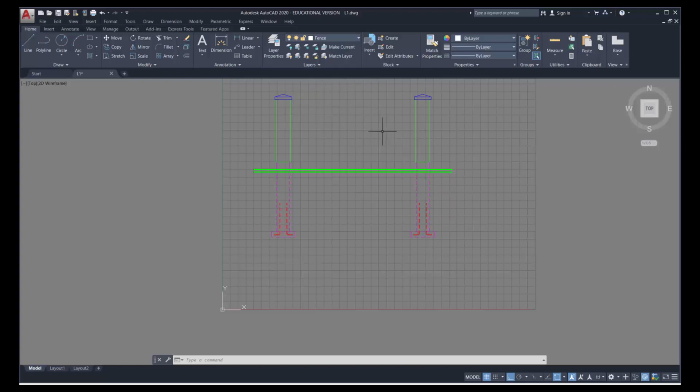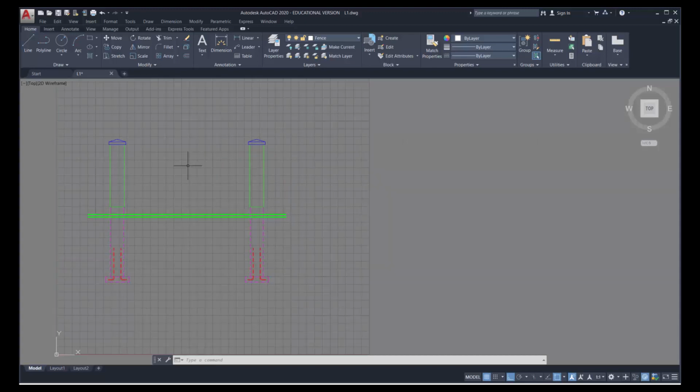And if you take a look at the diagram that's associated with this lesson, you'll notice that the gap between fence pickets is 6 inches. Now the picket itself is ½ inch. That's not dimensioned anywhere. The larger tubes that hold the pickets are 1 inch. So let's draw this. I don't have enough information to draw it in here, because see in the beginning there's a question mark. Now that's done on purpose sometimes, only because each of these gates may be manufactured by a wrought iron manufacturer who will site measure once the columns are in place to make sure they fit correctly, unless there's been an adaptive method of connecting that allows for some variance. We're going to make the assumption that there's not.